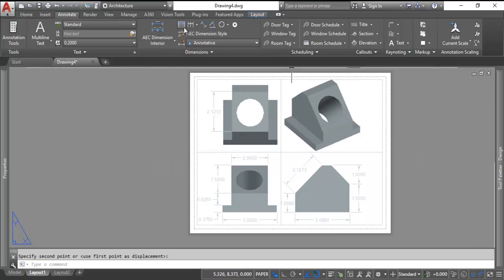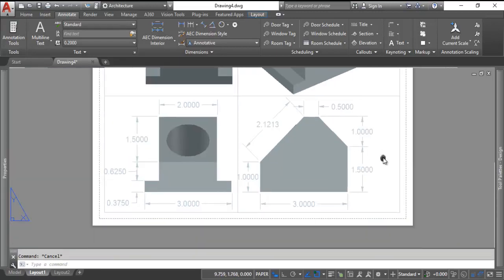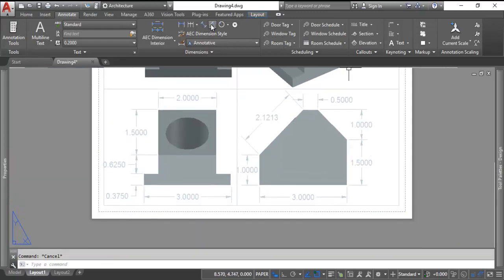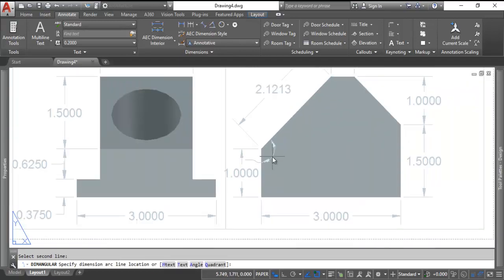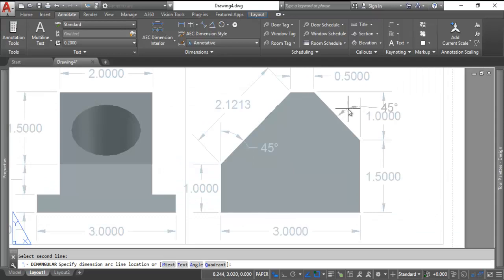And the only dimension I see we haven't given anywhere is this 0.5. And again, I can pick that, drag that to the other side so we're not overlapping. Perhaps an angle would be in order. We can do an angle by clicking two faces. We can go on the inside. We can go up on the outside. I'll probably do it this way on both sides. Click your two angles. We can go in, we can go up. We'll probably go up and then click once, take that grip point to move the text to the other side.